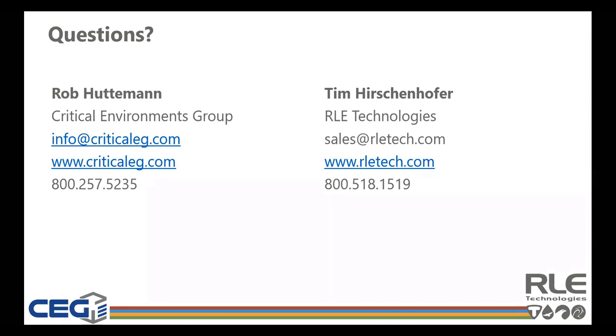I would second that. I think where we see hot aisle containment being implemented is in brand new build outs, whereas if you're in an existing data center, or maybe a slightly older data center, the option is typically cold aisle containment. The only other thing I'd mention about hot aisle is I think you probably could get a slight efficiency gain if you did an equal comparison between two rooms that were the same, hot aisle versus cold aisle. But you have to remember that those hot aisles can get, like you said, in the high 90s or even above that. And from a working environment standpoint, there are a lot of customers who just don't want their people working in the hot aisle when they're that hot.